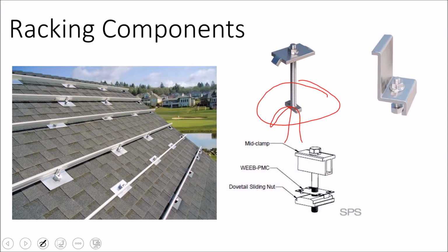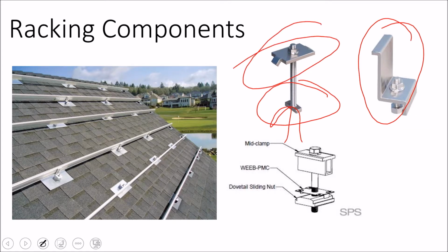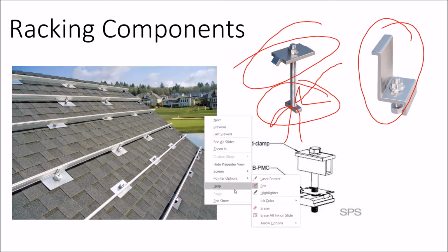That's a specialty component made by the racking manufacturers that you just can't find locally. You have to buy these T-bolts online, and you don't need extra clips. That clip isn't going to be damaged during the install. That mid clip isn't going to be damaged. If you drop it or lose it, there's no harm in having a couple extra in your toolbox. But as far as consumables, it's this T-bolt that is definitely worthwhile to order a few extra of.